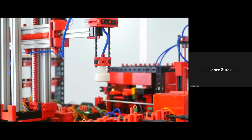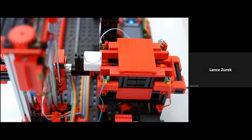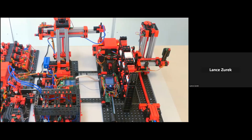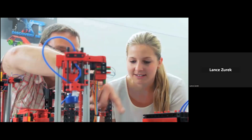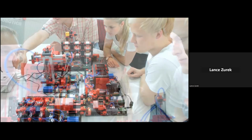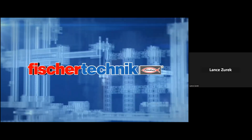First, this is currently available in the standard 24-volt version and in very limited quantities in a 9-volt version. In the instance of the 9-volt version, it's wired to 5 robotics TXT controllers, and because of this, it's going to require 3 120-volt power adapters. This is because a couple of the controllers are daisy chained, so we only need 3 power adapters. But as always, the 24-volt version will require the end user to provide any PLCs, any programming, any wiring, any additional hardware that's required. Again, each station of the 24-volt version does have the relay board for motor polarity reversal and both the multi-pin connector, 34 pins with a grid of 2.54 millimeters, as well as additional PCB terminals with push-in connections for all inputs and outputs.